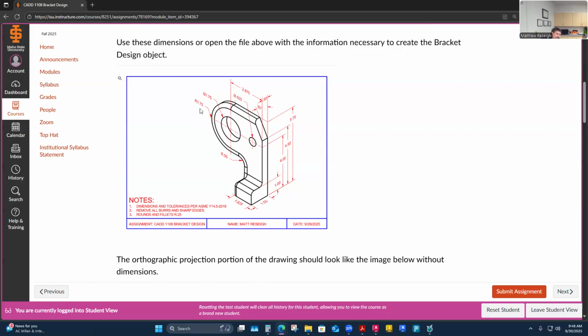And then my top view is going to become what would normally be the left side view. If this is going to be front view, base down, this is going to be top view, looking at the left side view. And the right side view is going to be looking right at this surface right here. So what looks to be the top as it's positioned is going to become the right side view. And what looks to be the right side view in this position is going to become the bottom. And front is going to be front.